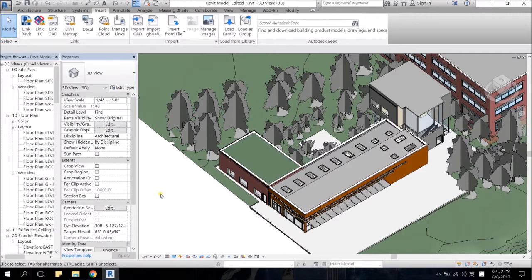With the help of DIVA, we can actually implement more daylighting analysis in addition to illuminance, such as useful daylight illuminance, UDI, as well as luminance. However, I decided to put more emphasis on the redesign within the Revit environment, and I will only mention the final analysis results in the following conclusion section.